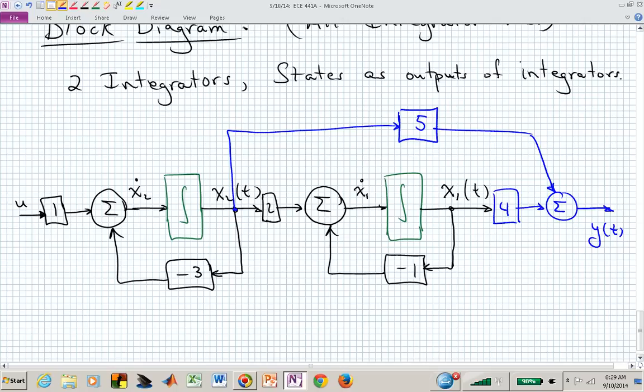If you had integrators, gains, and summing junctions, you could inject some electrical signal, u of t, that's representative of whatever it is that you're simulating in your analog computer, and produce the corresponding y of t, the output. If you put in a step for u, then what's going to happen to y? And this would solve that for you. This solves your differential equations.